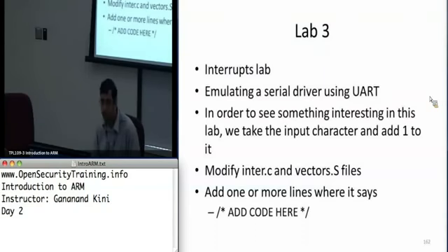All right, so this brings us to the interrupts lab. For the interrupts lab, we won't be using the QEMU emulator with the setup for Linaro. We'll be using a bare metal simulator, simulating an ARM 926 EJ chip, which is an earlier architecture, ARM v5, but I thought it would be good to get a feel for how these interrupts work.